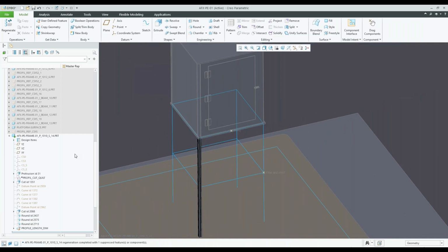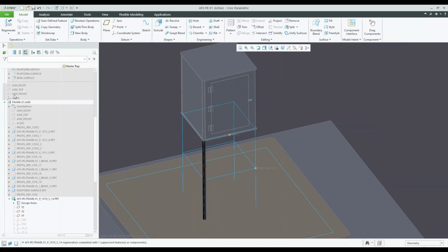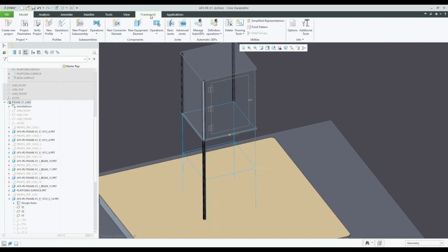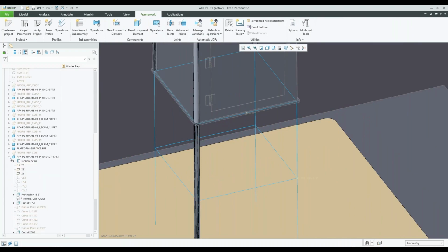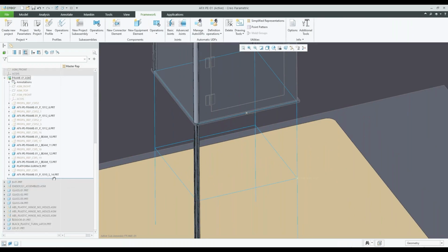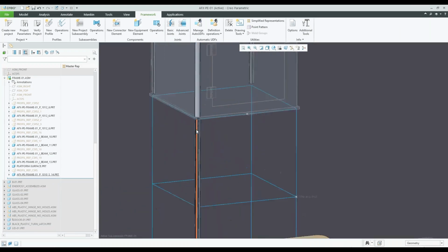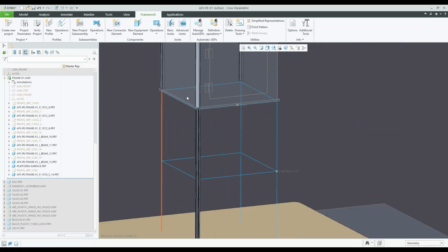Okay. And what's great about this now is if I go back to my frame assembly, subassembly level, and go back to framework, you're not going to want to create new part numbers if you're using the same lengths, for example. So if this vertical support leg here is going to be the same for all of them, which it should be, you can just reuse that profile.